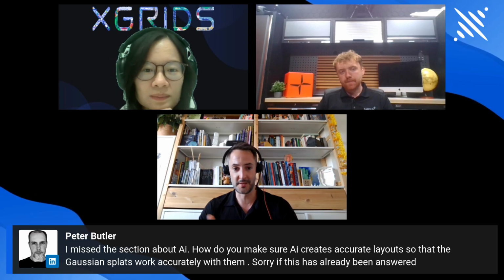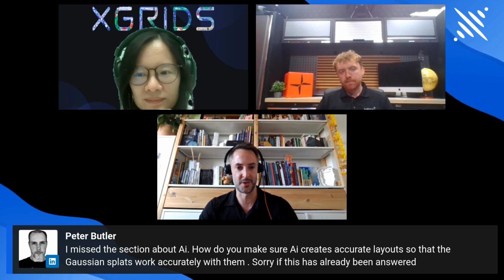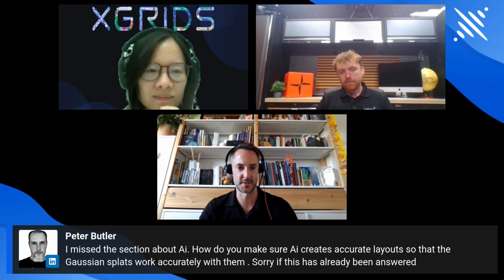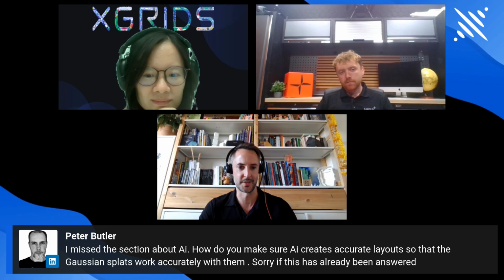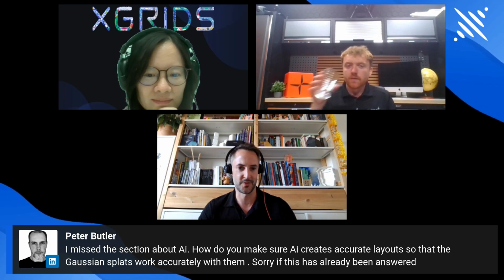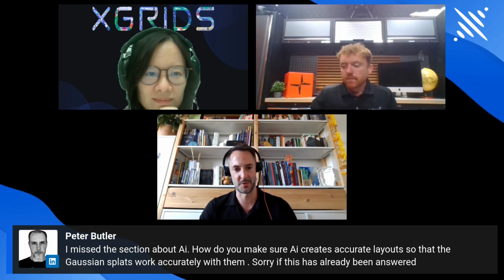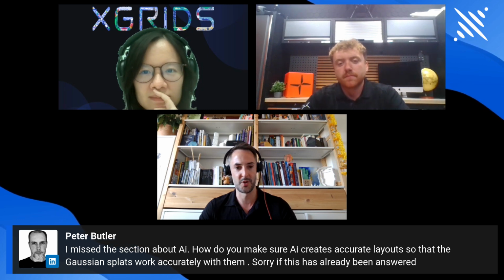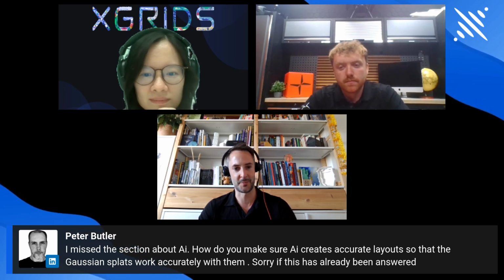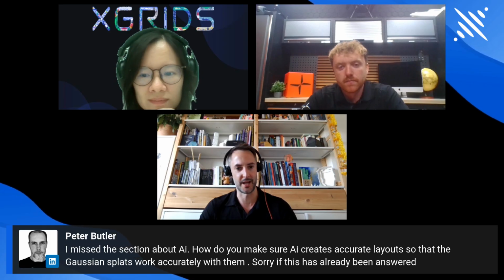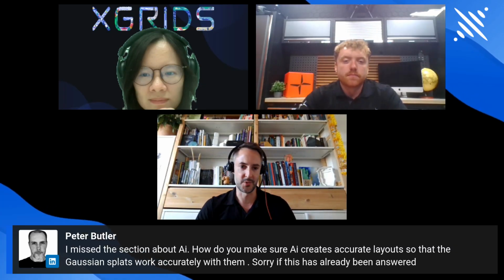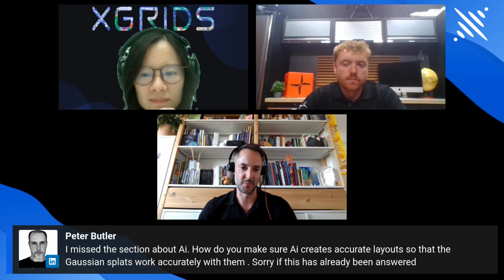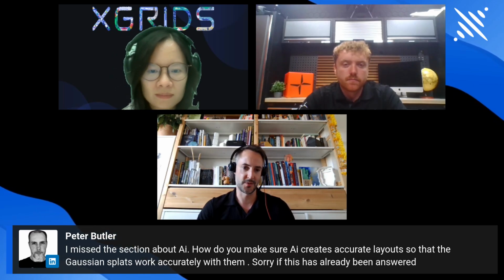But now that Alex was talking about the fusion ground control, so the fusion system where you add more images from the drone and everything, I find it an incredible system. The fact that you can inform the construction of the Gaussian splat with image data sets from a drone, I use it a lot because that's very useful to capture things that you cannot capture from the ground level. When you need to create a Gaussian splat, if you go with the scanner around a building, you don't see the roof or the top features of the geometry.